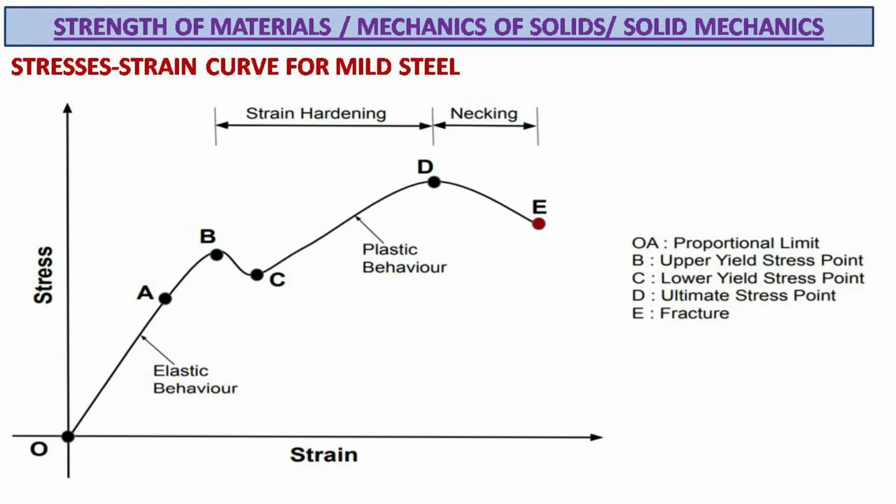Slide 19. In this slide, the stress-strain curve for mild steel is shown. All the important points are plotted on the graph. Point A shows the proportionality limit. Point B shows the elastic limit, and zone OB comes under the elastic zone. Beyond the elastic zone the material enters into the plastic zone. Point B is the upper yield point. Point C is the lower yield point. Point D gives the ultimate stress for the tested sample. And point E gives failure stress. Mild steel gives a definite yield point when tested. Stress corresponding to the lower yield point is taken as its yield stress.